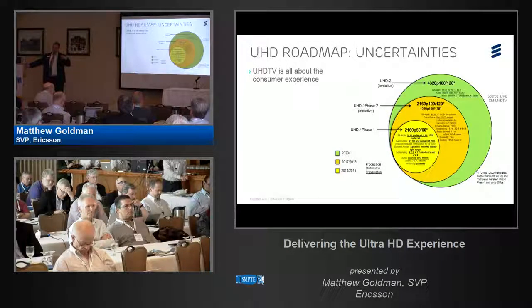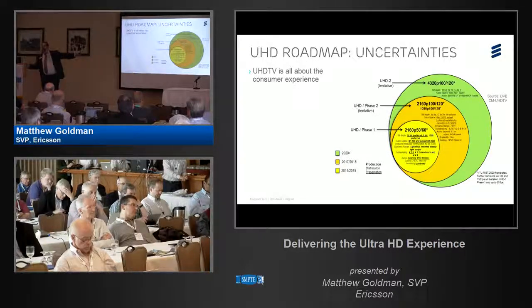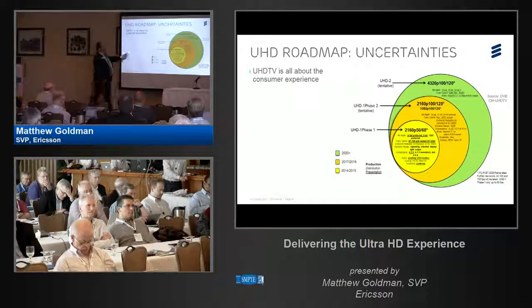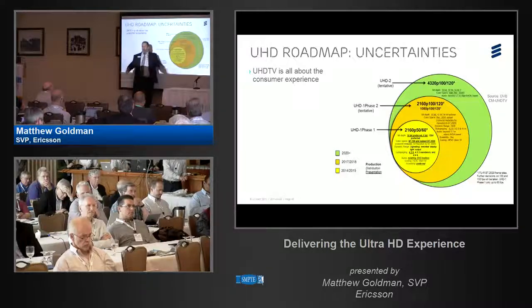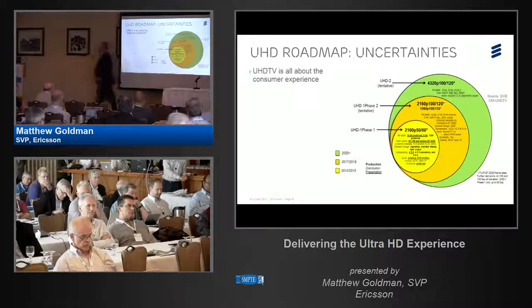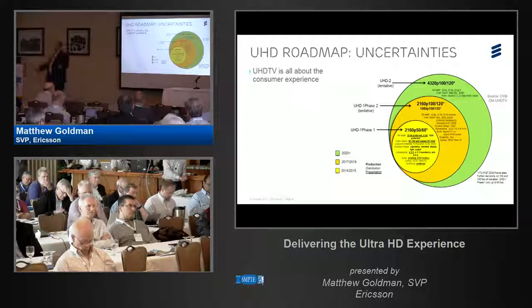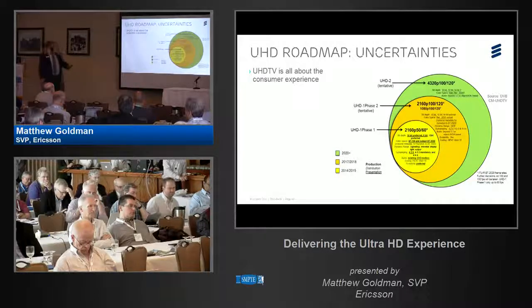2160p100, 120 because they just don't think it's practical in the time frame. So there's a desire by the industry to do something to make a difference, where we're just basically throwing a towel in and saying the complexity to do that actually requires a higher level in the HEVC standard. If you know HEVC, it will require level 5.2 to do this instead of 5.1. It's very complex. The chips don't think it's there. There's extra data paths they have to put in there. Again, it's on the consumer side. They just don't think they can make it economically viable in the 2017, 2018 timeframe.